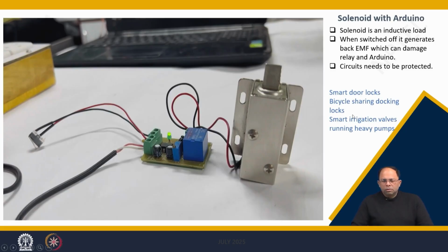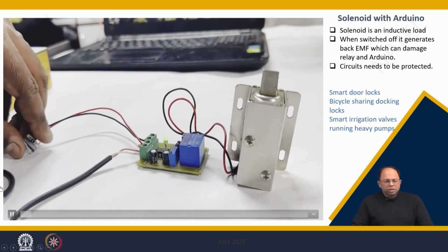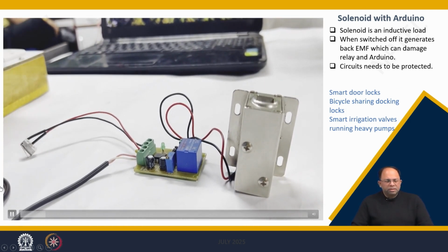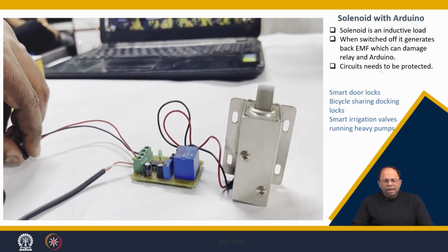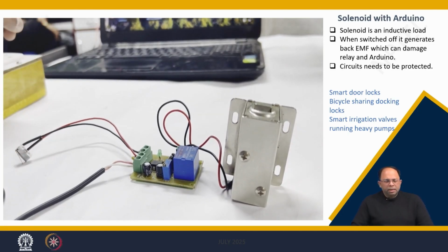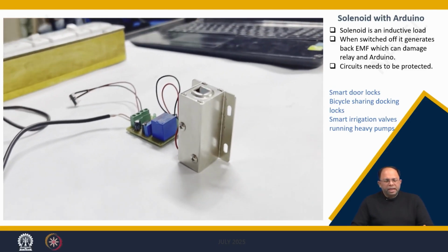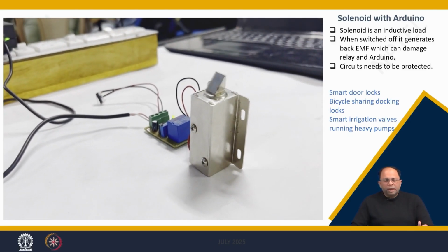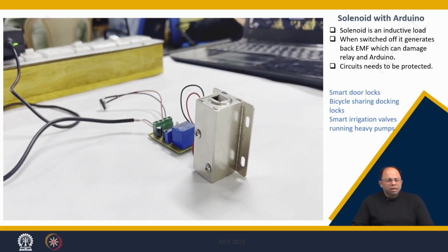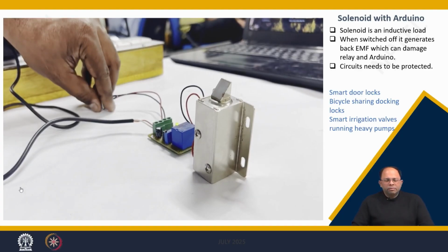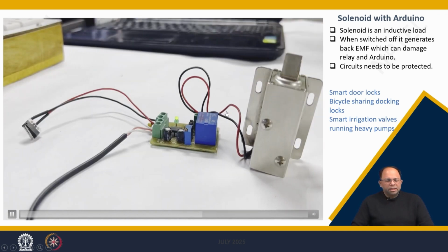At the same point of time, you can see over here we are demonstrating it. We are using a limit switch as well to send power to that particular relay. We have used a limit switch just to complete the connection, and as soon as we turn it on, the solenoid gets operated.